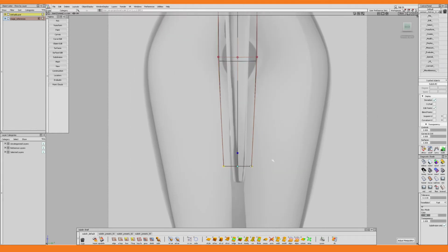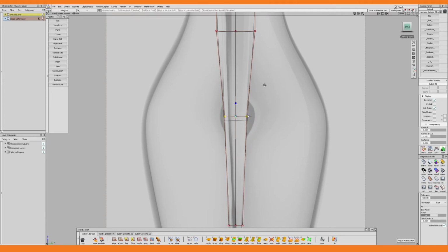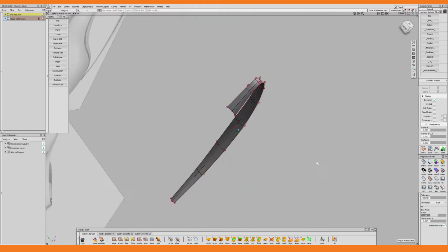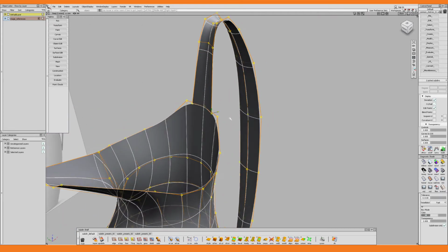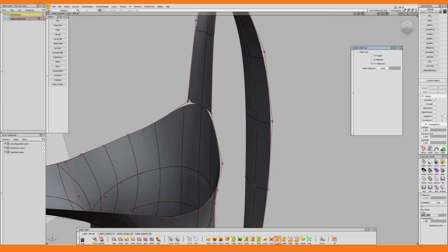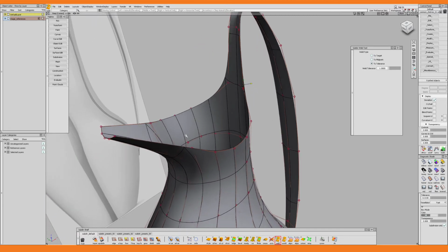And then it's just a matter of tracing the handle in the rear view as well. And this should be second nature to you by now. Now I want to combine the two objects back into one. The first step of doing so is by snapping points to each other by holding Ctrl and using the Move tool. With the Weld tool set to tolerance, I then drag select over the vertices to weld them together and create one unified object.